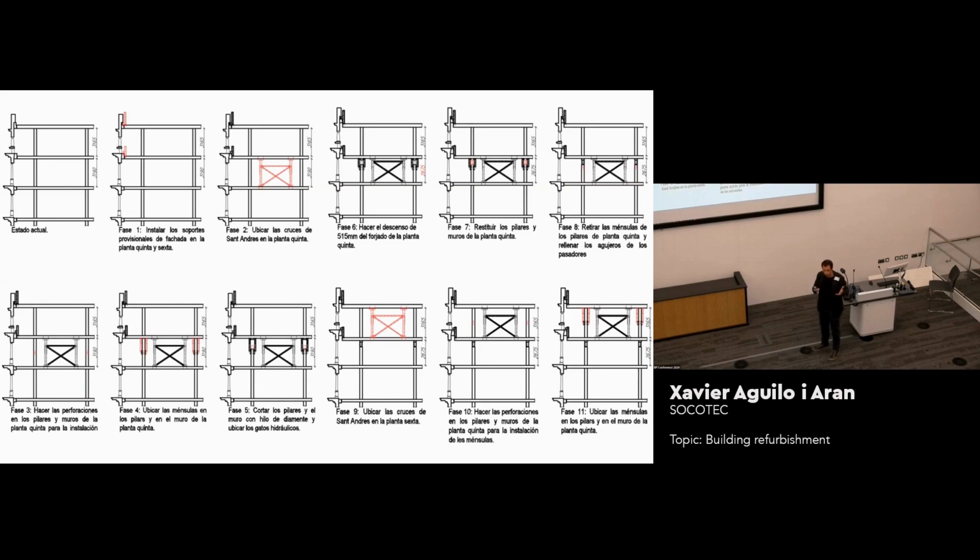But whenever you do something weird like this, you need to take into consideration that you are cutting the building. So the horizontal forces need to remain stable. That's why we need to put this bracing in the middle of the building. We need to do cuts that transfer the loads with artificial elements that you will remove afterwards. And you need to use jacks to do that.